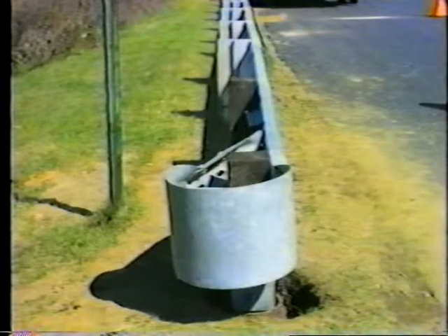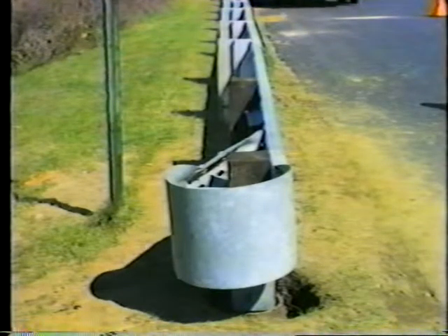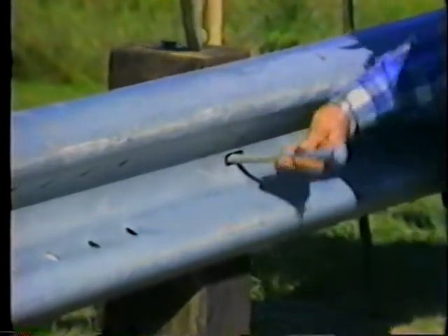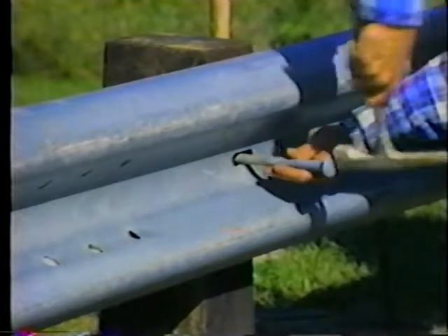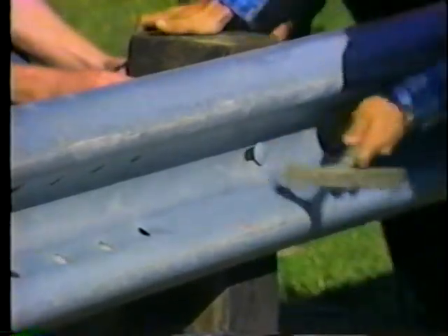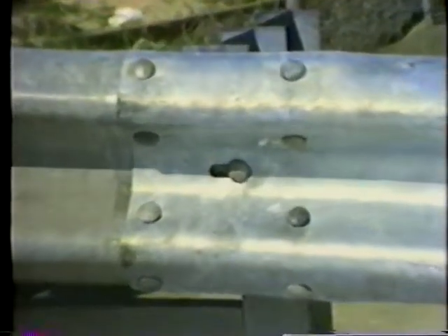After the first 2 posts, blockouts should be used. No washers should be used on the first 8 posts of the W-beam post connection bolts. This allows the railing to tear loose from the post and to bend outward more easily on frontal impact. Leaving off the washers on all post bolts is acceptable practice. Check your specifications for guidance in this matter. Finally, recovery space is a major consideration when a BCT end treatment is used.